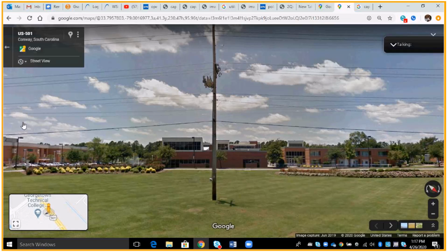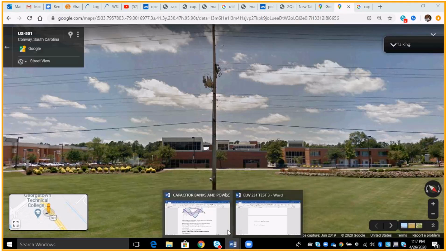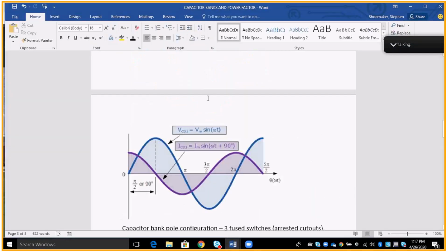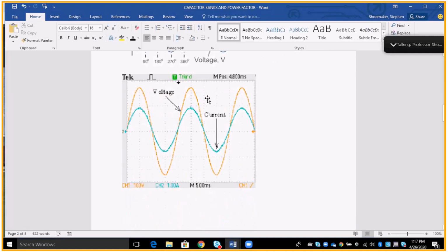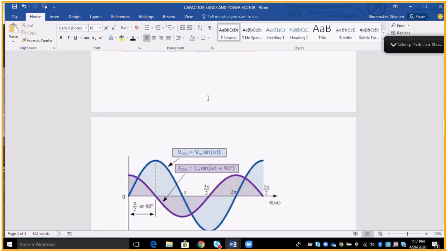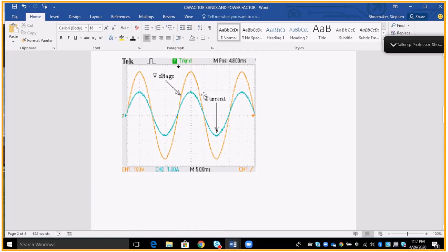My amperage won't lead as much, and the voltage is going to come more in line with the amperage. That's how it knows if it changed. Okay, and it's actually just reading power factor. When I talk about power factor, and when you hear about power factor, these three diagrams are it. Either a current leading, or a voltage lagging situation, or a resistive circuit.